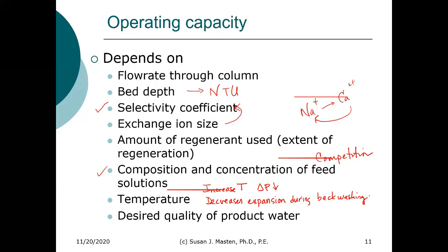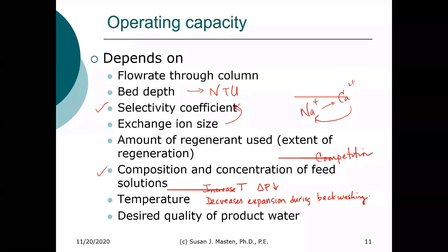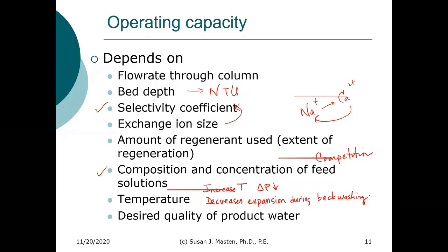During backwashing, we will fluidize the bed, and that will help release any solid particles that were captured. It also allows for better regeneration. And backwashing can also help with removal of organics. And finally, the desired quality of the product water affects how much water we can treat to the point where we have to regenerate.